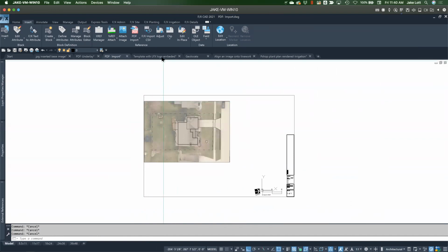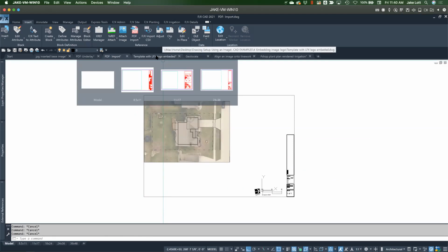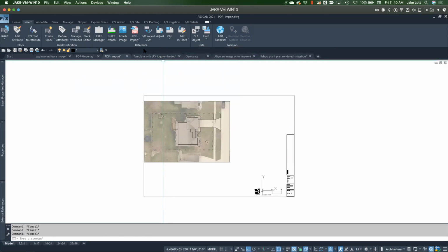I think a couple of people chimed in with some great tips for Google Earth. Eric reminded us that you want to make sure it's in vertical mode. You don't want a little bit of perspective when you grab the image. Always be sure to click that button. And someone also mentioned to check the historical photos. Sometimes those can be better. I've seen where the most recent photo is a little too recent, you've got all the construction equipment there, and it's nicer to get the cleaner site. Those are great tips, and I might even show you one more as we get into the Google Earth one.